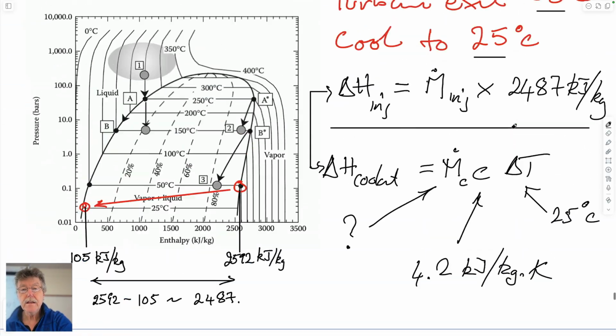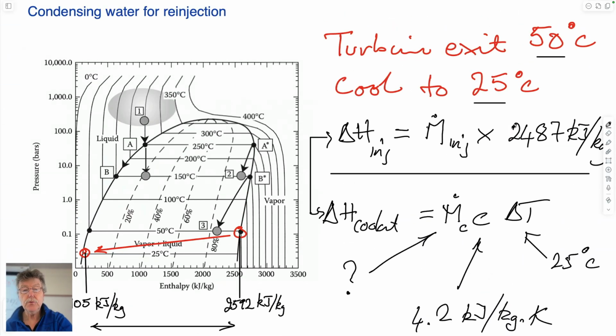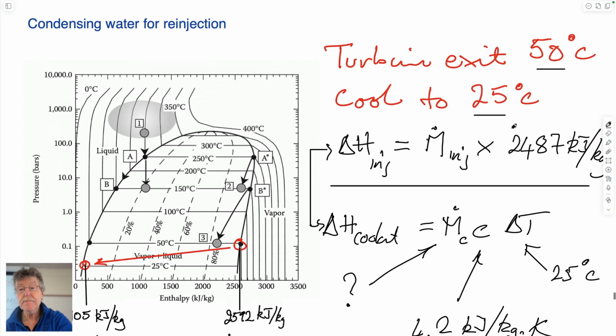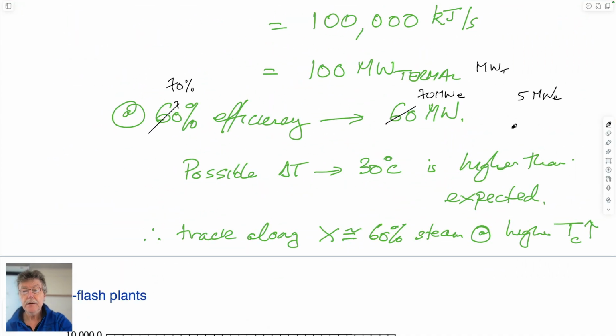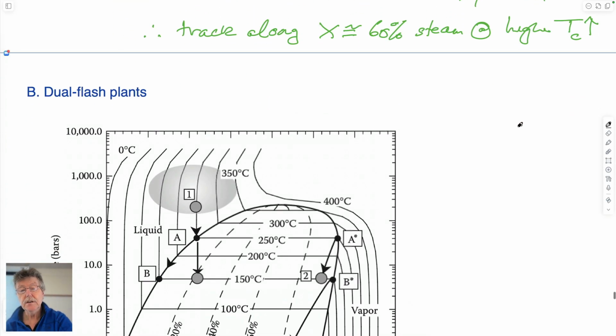So that's a way to be able to calculate how much energy we get out of the system. Obviously, in addition to this power that we get out of it, we'd have to subtract off the parasitic losses. So we have to pump water maybe to the well and raise it up a couple of kilometers to get it into the turbines. So that would be a net loss in the system. And we also have to condense it, compress it, and pump it underground, potentially under pressure. So those are two parasitic losses that would end up being in the energy budget that would detract from the amount of power that we recover from the reservoir.